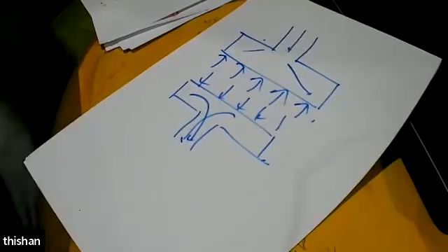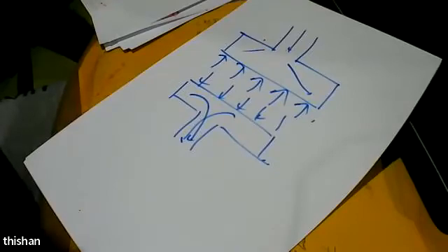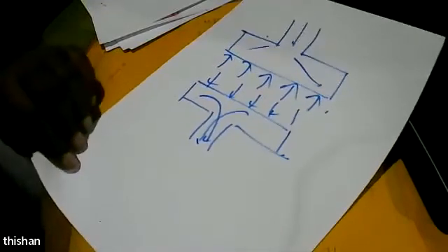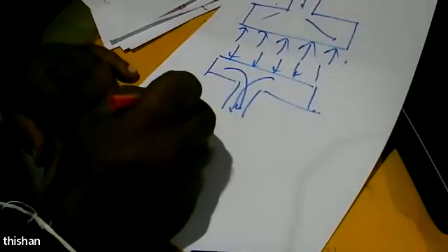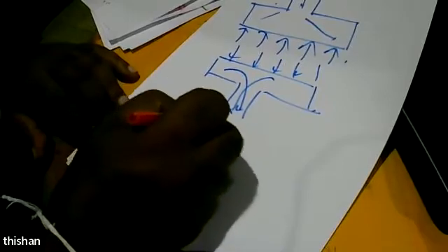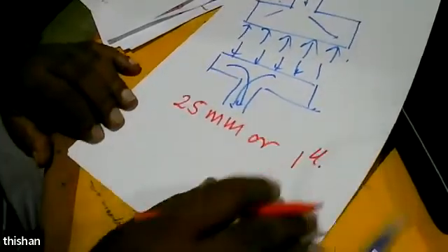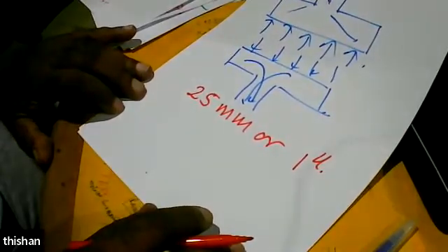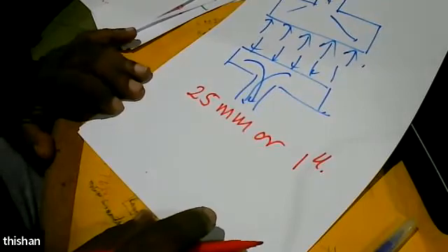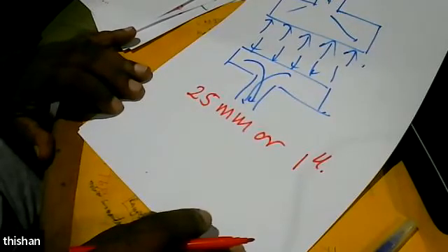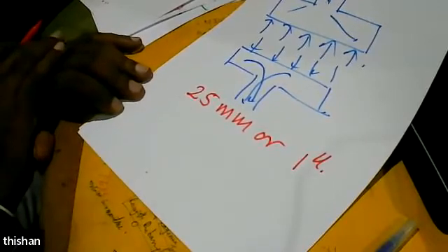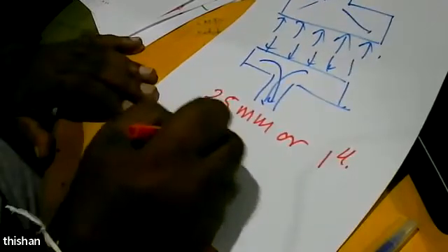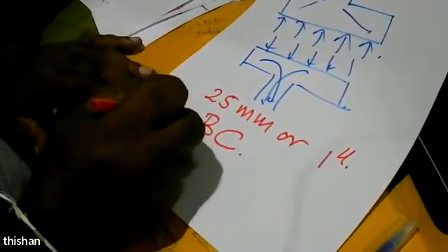The whole idea is you get a concentrated load from the column, which is resisted as a distributed load by the soil. And then you'll ask why it needs to be distributed: because the maximum allowable deflection is 25 millimeters or 1 inch. If you want to control the deformation of the soil to 1 inch, the load needed to limit it to 25 millimeters is called the bearing capacity. So under service conditions, it's the bearing capacity.